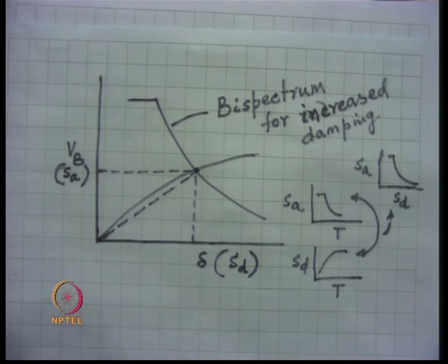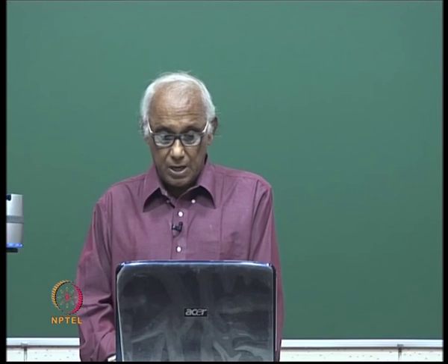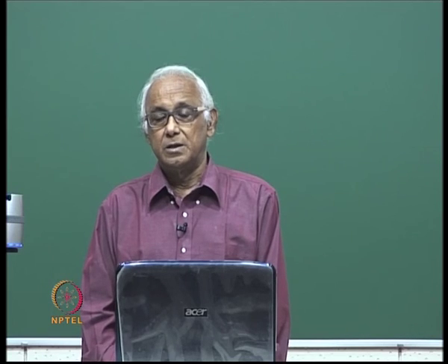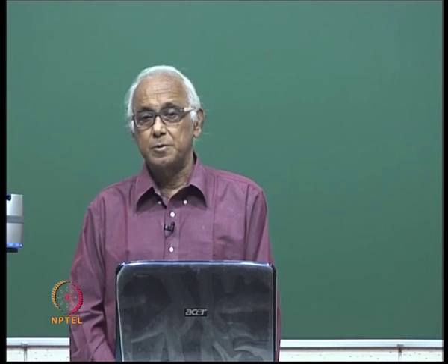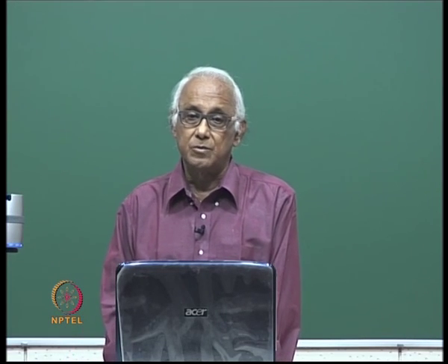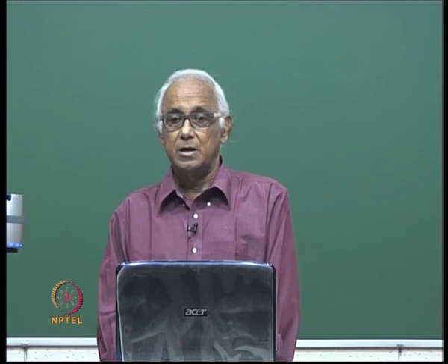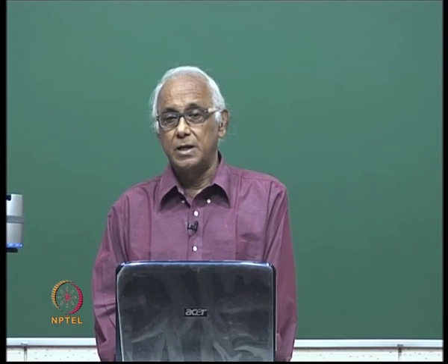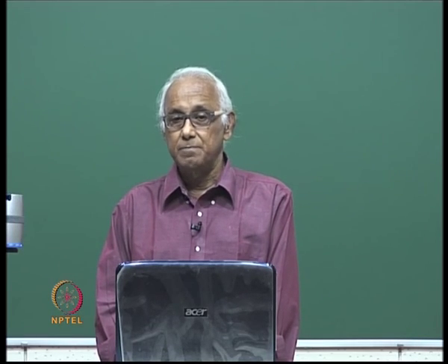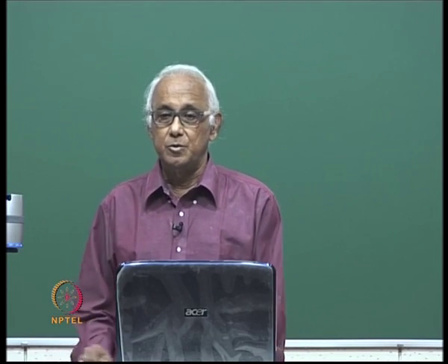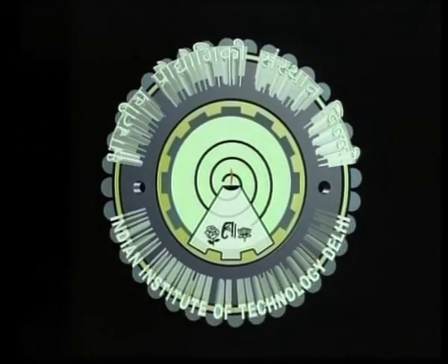and from there one can obtain the value of the required ductility, that is, the maximum displacement that we obtain divided by the elastic displacement. When the structure first gets into the inelastic state, or the first plastic hinge is formed, that is taken as the yield displacement, and delta becomes the final displacement. The ratio between the two gives an overall ductility for this system.